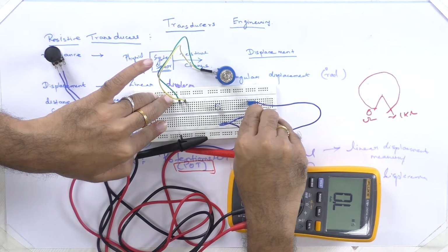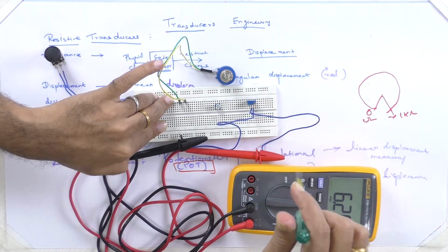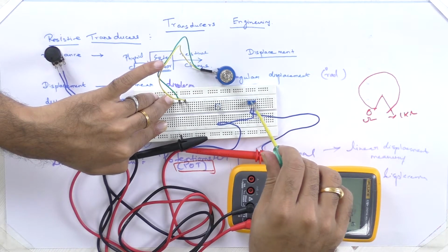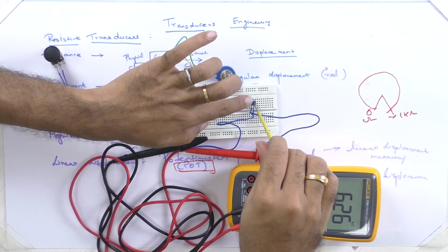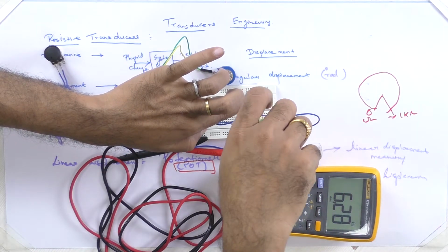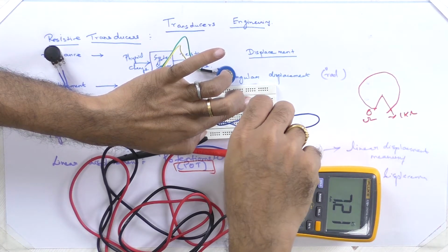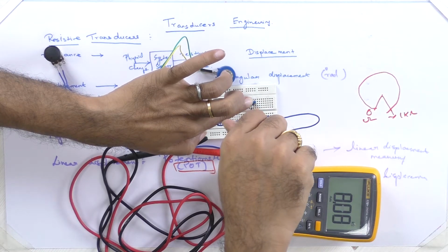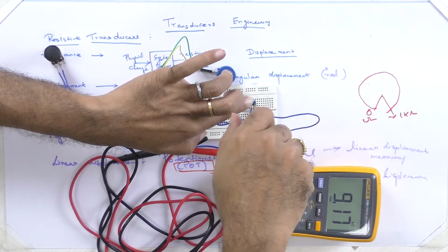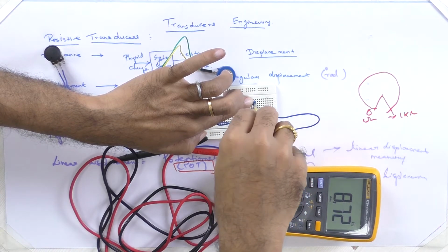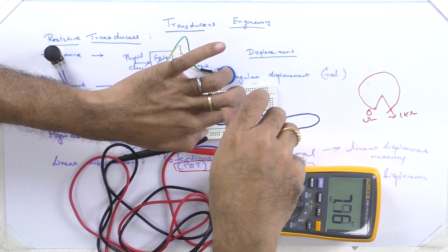These are very useful in PCBs, printed circuit boards, you will study. This is a 10 kilo ohm pot, so again many adjustments are possible. See here, I can go through many turns and it goes till 10K. It's also a helical pot. Inside it has many turns, and we can make many precise measurements. So from this itself you can see I am making many turns, coming down now.